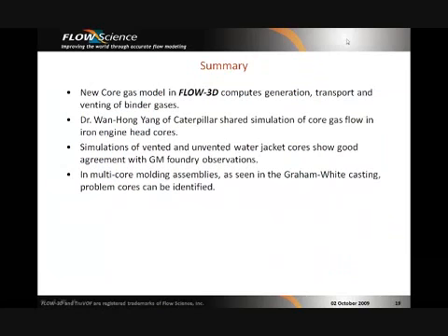To summarize this presentation, a new core gas model in Flow3D computes the generation, transport, and the venting of binder gases. Dr. Yang of Caterpillar shared his results of core gas flow in engine head cores. Simulations of the vented and unvented water jacket cores show good agreement with the GM foundry results. In multi-core molding assemblies, as seen in the gearbox casting, problem cores can be identified.